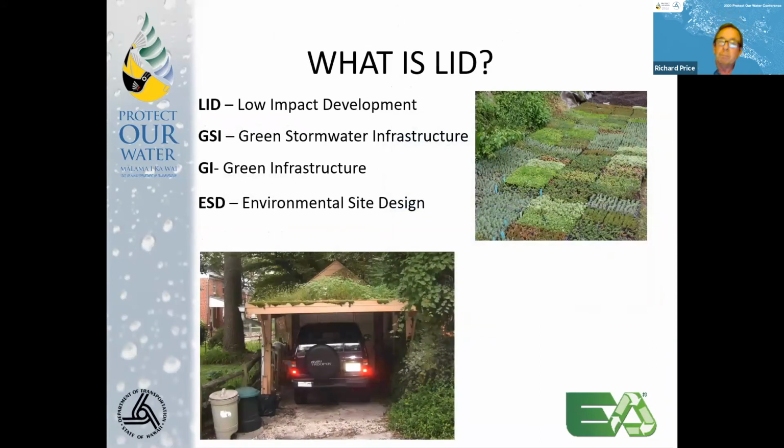So what is LID? Low impact development. Some places now they're calling it green stormwater infrastructure or green infrastructure. Environmental site design is more related, I think, to subdivision type development, where they talk a lot about site fingerprinting and the idea of only disturbing as much land as needed. Not as applicable to linear projects like roadways, but can be, because the concept of the less you disturb, the less you need to treat is always beneficial.